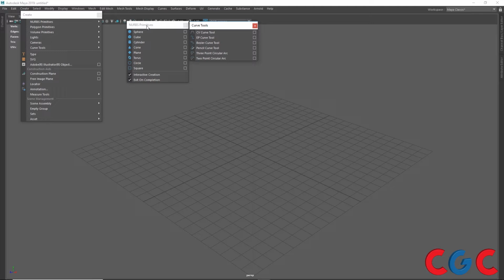So when we are working with Nurbs, we are going to work with curves parallelly, so they are going to be in tandem, where we are going to create things using curves, and from Nurbs we will convert it into polygon. So the reason we are not using Nurbs from 0 to 100 or till the rendering or animation is when we get into unwrapping, rigging, those areas, controlling polygon is more comfortable than Nurbs.